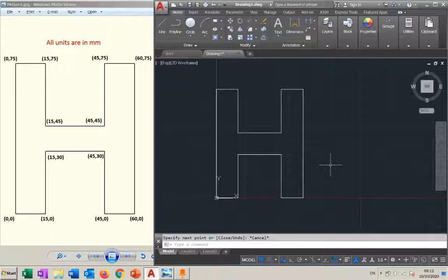The other way, the easiest one, when you made a mistake, it's okay, accept the mistake, hit the enter. The line will be drawn by mistake, but you can simply take one step back by using Control Z on your keyboard, which is the easiest way. That line will not be deactivated by Control Z. Line is still active. You just simply delete one line and you continue with the place you were stopped.